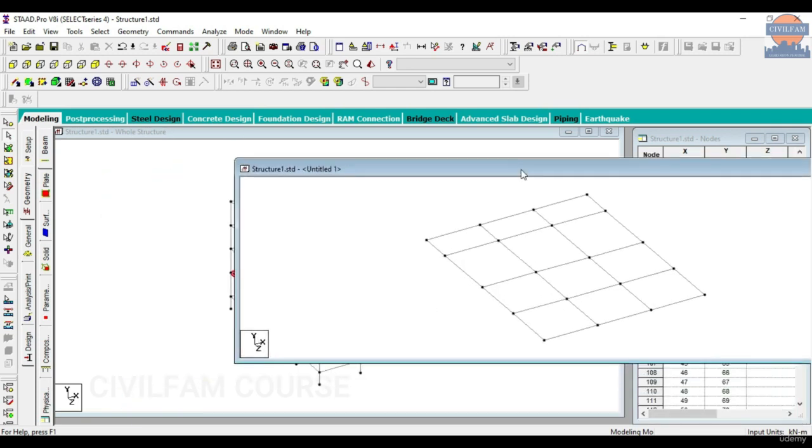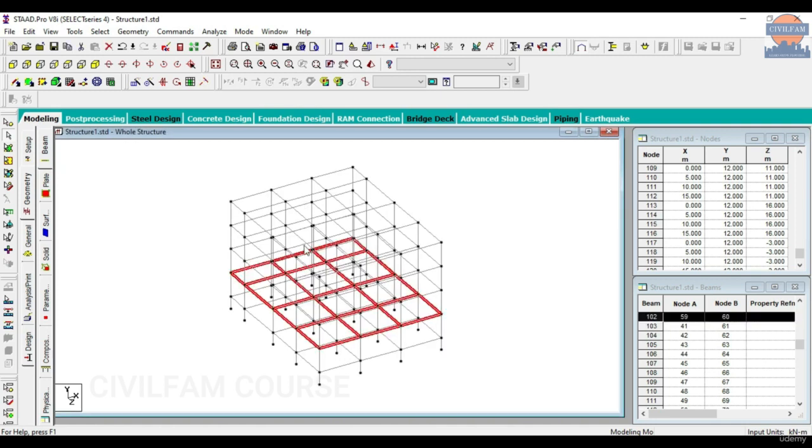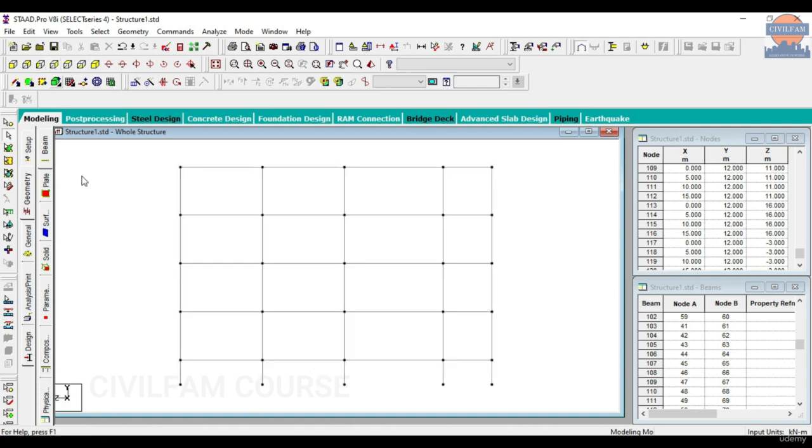Now this, what I just taught you, is very important when it comes to checking out your bending moment diagrams and shear force diagrams. Okay, just imagine trying to see bending moment and shear force for the whole structure. It looks very messy. You won't be able to understand what is what. So at that point, all you have to do is use these 4 or 5 views. Come in any view that you feel like, just select the floor that you want to see.